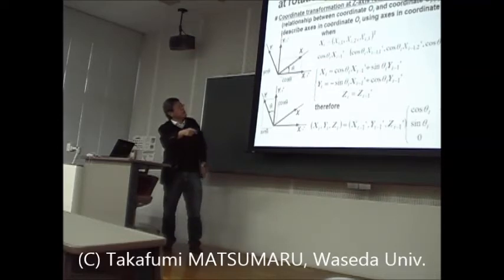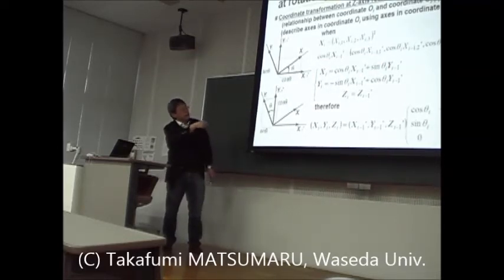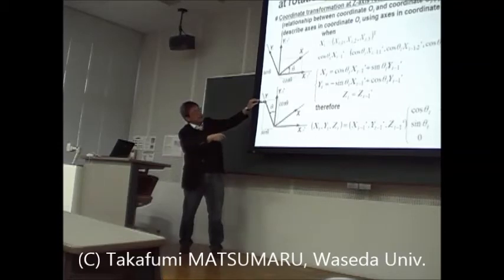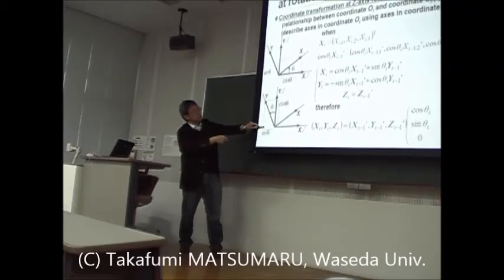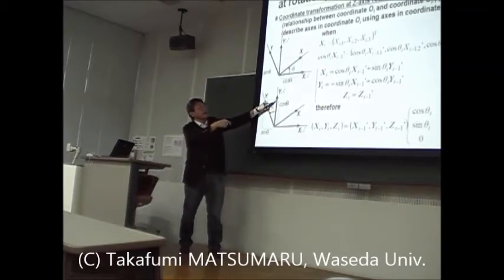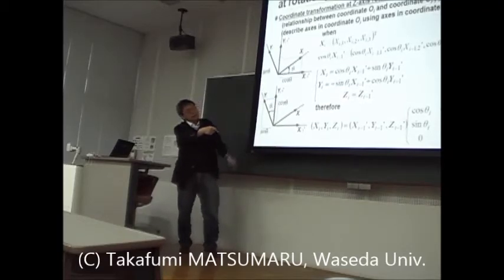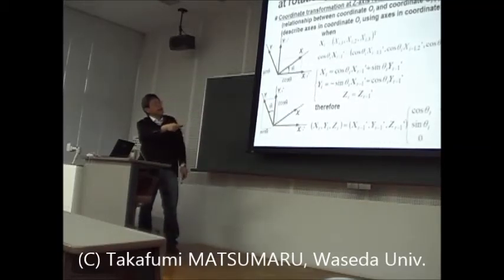Okay. It is also the same for the new y unit vector. How do we calculate this new y unit vector? It is the x-direction vector plus the y_{i-1}-direction vector. This is a minus sign, because this is the opposite, negative direction along this axis. So this is minus sine theta_i here, and plus cosine theta_i here. The size of this vector is cosine theta. Therefore, y_i is minus sine theta_i x_{i-1} plus cosine theta_i y_{i-1}.